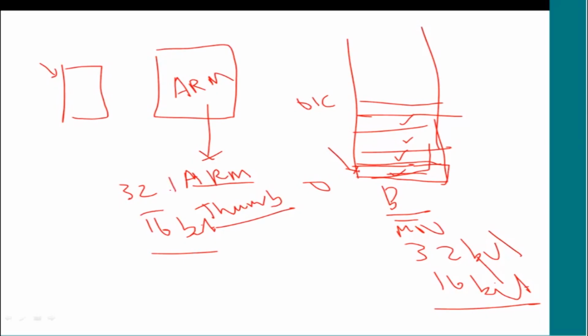So through some means of CPSR, you have changed the mode of the processor and it is in Thumb mode. It is executing 16-bit instructions. Now an interrupt happens. Suppose you say that you want every ISR handler or the vector table to be independent of ARM or Thumb mode, then what happens? Suppose the ARM processor continues to be in Thumb mode and then tries to access the vector table. It will interpret these instructions as 16-bit instructions, isn't it? It won't interpret them as 32-bit instructions. Then what will it conclude from it? Something else, not what the programmer intended. So that's a confusion, right?